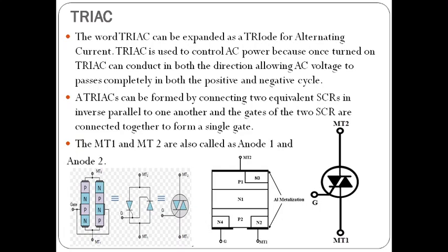So it is looking like silicon control rectifier, but in the silicon control rectifier we are having the three terminals named as anode, cathode, gate, but here we don't have anode and cathode separately. Here we are having two terminals named as anode 1 and anode 2. We don't have cathode. Otherwise, you can say it is MT1, MT2. You can observe the diagram in this slide.